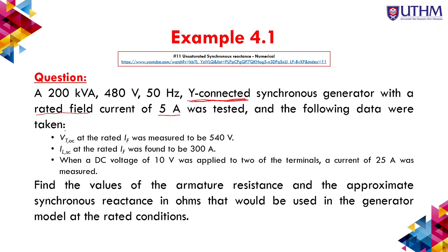So they get it as a VT. At the rated IF, it was measured to be VT open circuit equal to 540 volt. And then IL short circuit, at the rated IF, was found to be 300.